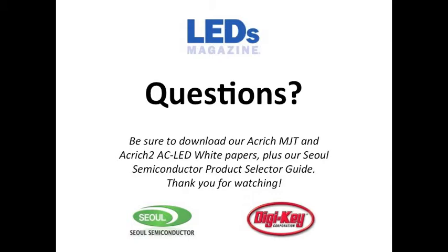So typically, when you have an application that requires a certain beam pattern, if you're going to use a secondary optic on top of it to focus that beam, a dome type package is going to give you a more even light output than a flat top. It really doesn't have to do with MJT LEDs, it's just the type of LED, whether it's a dome or a flat top. The flat top is not going to be as even light output, so the dome gives you the capability to really focus that light and have an even light output from that type of product. So it doesn't really matter whether it's MJT or not, it just has to do with the package style.